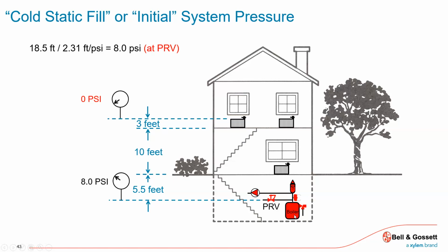Same, 0, no motive force. So an industry standard was always, whatever it takes to get to that high point, add 4. You'll see it written everywhere, all over the industry, add at least 4 to 5, it can't hurt. But now, at least if I have those vents up there, and I have this body of air, bubbles gather around that can, and the can falls down, gets displaced by the weight, I've got 4 pounds of pressure going to 0. So I've got motive force to get rid of the air.